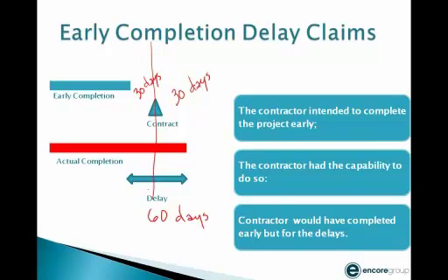One of the best scenarios, in my opinion, is to let the contractor show the schedule that he intends to perform by, but then hold him accountable. I mean, week 1, week 2, week 3, starting at the very beginning of the job, start documenting: is the contractor meeting his schedule? If he's meeting his schedule and he's got an early completion date, there's a good chance that he might finish early. And as an owner, everybody looks good if you finish early. So that's just one of the big issues.